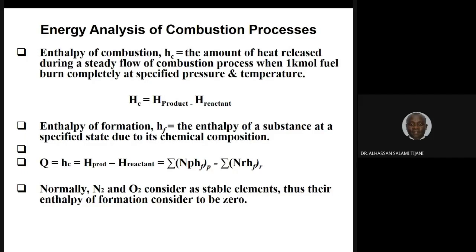Here we have h_C, the enthalpy of combustion, which is the amount of heat released during a steady flow combustion process when 1 kilomole of fuel is completely burned at a specific pressure and temperature. This can also be referred to as h_R, the enthalpy of reaction, which is the same as the enthalpy of combustion. So it is a difference between the two enthalpies.